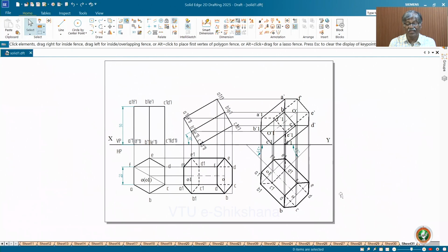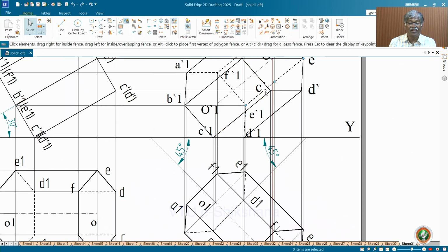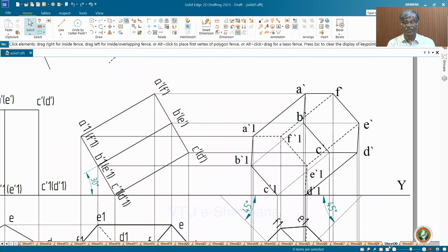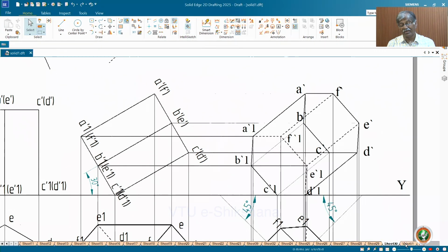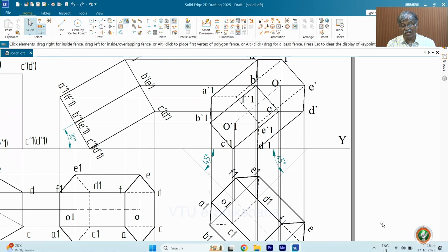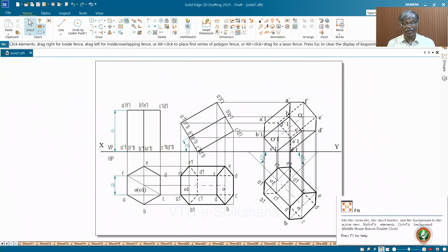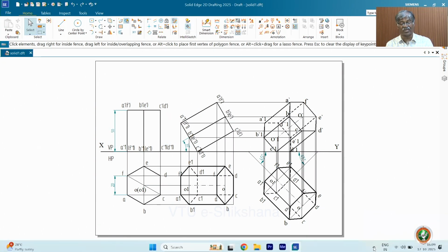Similarly, you can have the other things like this one. Start with bends, clarify with crossing line, and get confirmed with the invisible surface, visible line. So it's very interesting. You can always use any approach, but don't get confused much because of the methods. Whichever the method, you can clarify with bends and crossing line. That is always true. And also sometimes neither bends nor crossing line works. Only visible surface, invisible line. Invisible surface, visible line. That is the fundamental concept that works anytime.